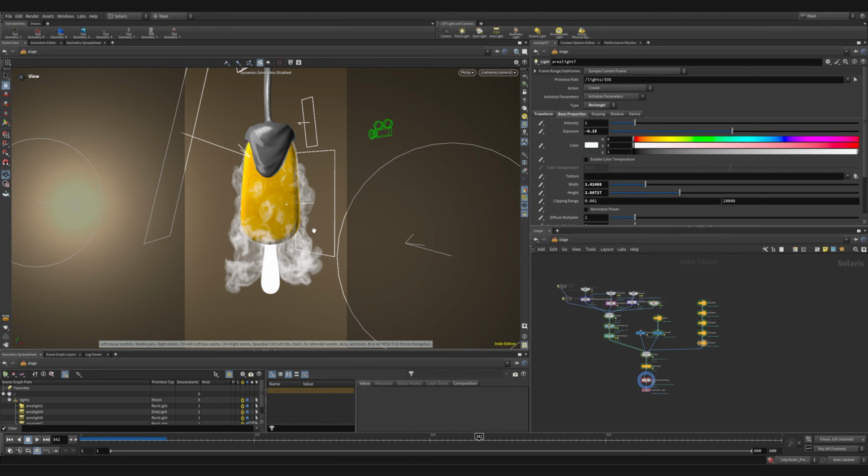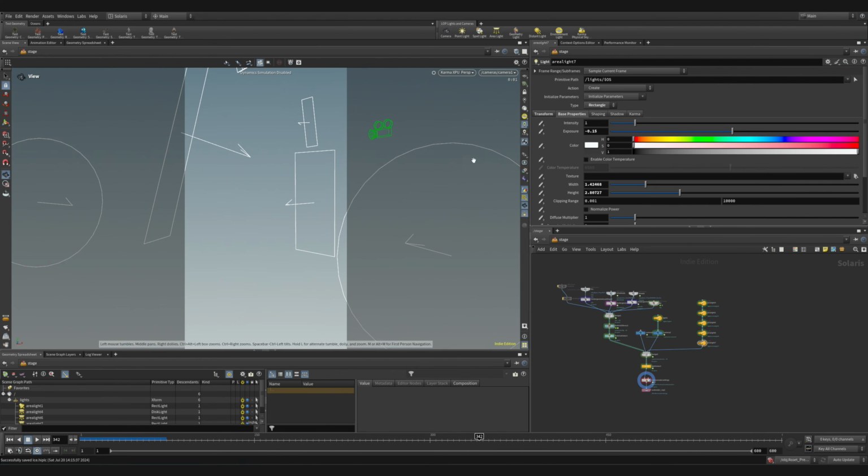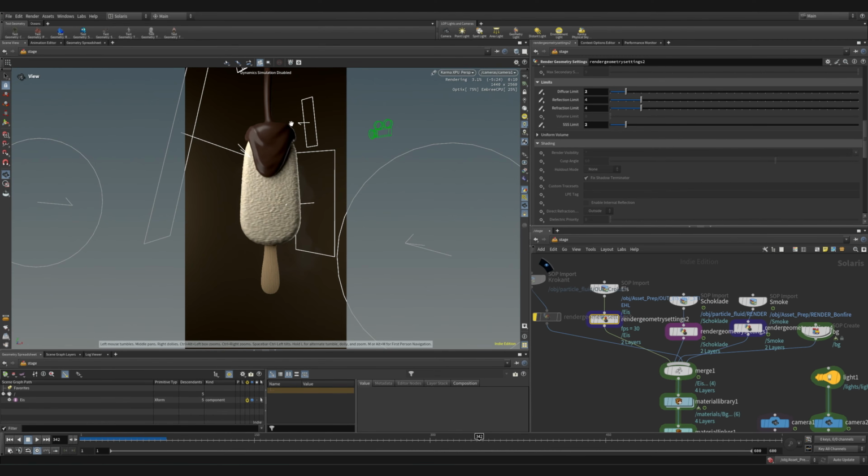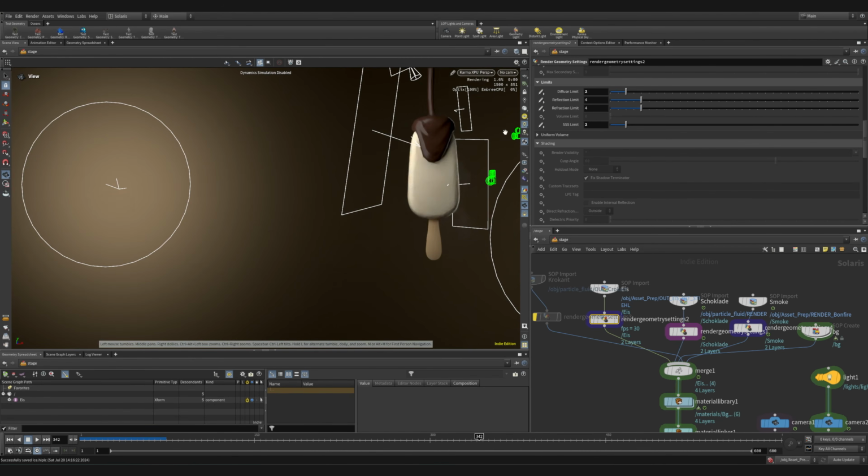Let me just quickly explain. We have the rim lights here. So if I just quickly save this and swap to Karma. What we have is the two rim lights here, these and these. They come from behind, so they create this nice light edge, which helps to separate the product from the background. Then we have this one key light here, which comes slightly from the side, but from the front, to light up this main side of the product. And then we have the two lights for the background, which is this one, and they just directly shine onto the background, which I just used a giant grid for.